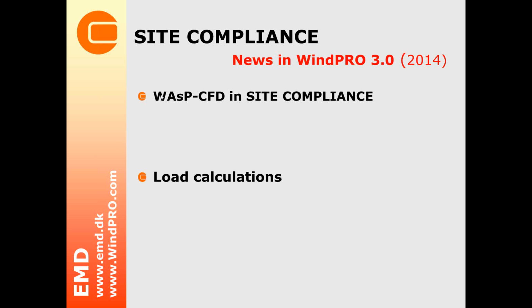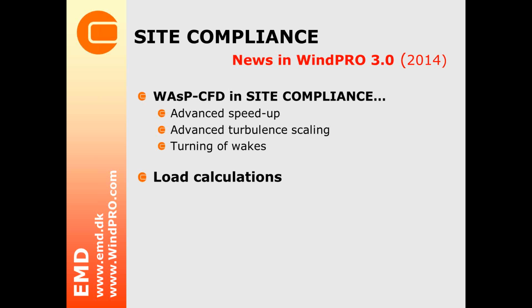One is related to introduction of WASP CFD results in site compliance, and the other is related to the development of load calculations. And we're working on these things right now. The introduction of WASP CFD calculations will allow some advanced speed-up calculation options and also advanced turbulence scaling. And we'll have more detail in also accounting for the turning of wind turbine wakes.